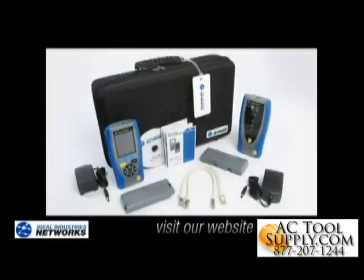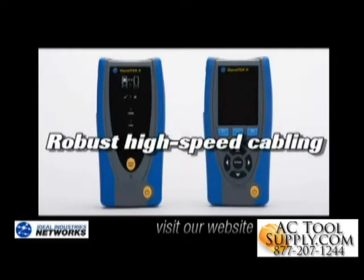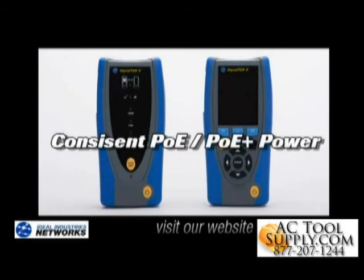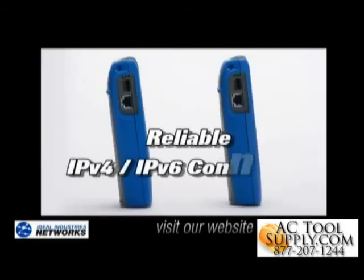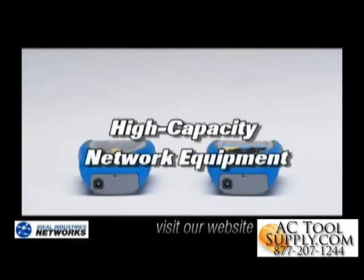Now, in summary, the SignalTek II allows me to test and troubleshoot the critical infrastructure components that I need in order to support this high bandwidth IP camera installation. And that's namely the cabling in the wall, making sure it supports, say, Gigabit Ethernet. We want to consistently make sure we have Power over Ethernet delivery to all these cameras, and reliably look at the IP version 4 and IP version 6 connections. And lastly, make sure the high capacity network equipment can support these cameras.